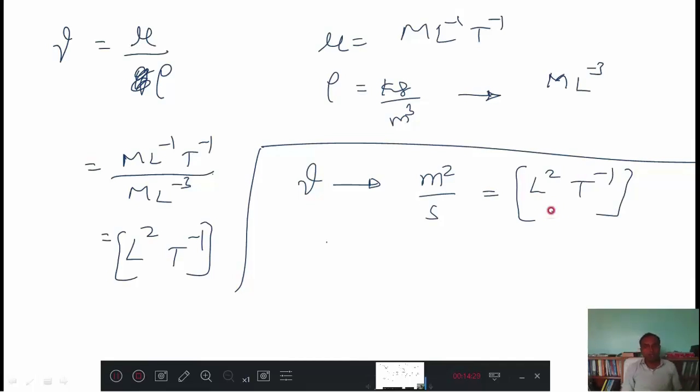Okay, you can come by basic equations, basic parameters, and substitute in that and get it, or otherwise directly remember the unit of the parameter, and after that substitute the MLT corresponding to that, then you will get the dimensions. Like that we have many, for example, density, specific weight, dynamic viscosity, pressure intensity, modulus of elasticity, surface tension, shear stress, work, energy, power, like that many are there. You need to try for them with the basics and by knowing their units. Okay, just refresh what you studied previously, or otherwise whatever parameters I told now, make a list and make the dimensions of them.